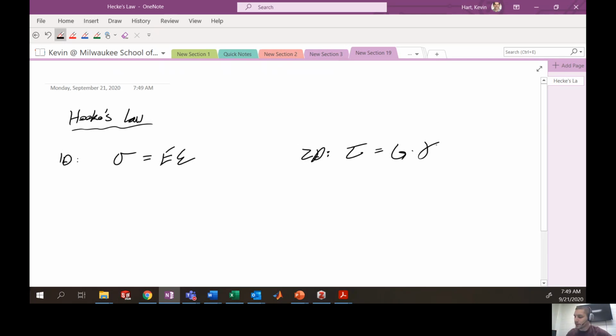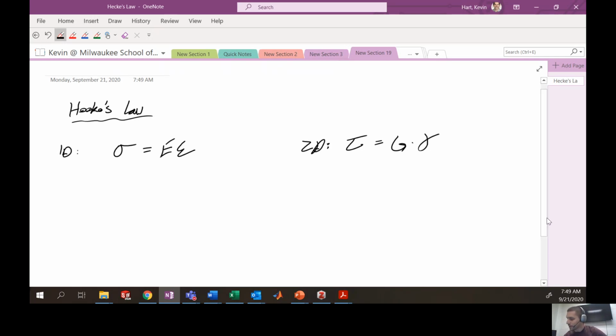All right. So what we hope to accomplish in the lab is we ultimately want to calculate the elastic modulus E and the shear modulus G. So I'll put that this is the final goal. In each one of these two equations, we're going to need to calculate the stress at each point of interest, and then also look at the strain at those points of interest.